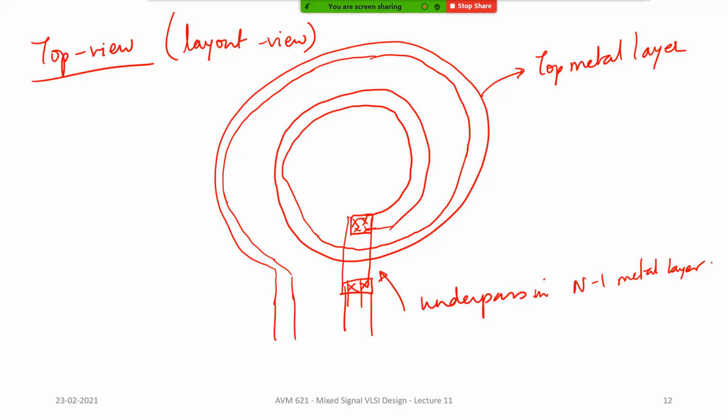So this basically has a certain outer diameter, width of the line, and then you also have spacing, right? This is the spacing, and number of turns. So all these factors basically determine the L and also the Q. Of course, what is not in your control is basically the thickness and conductivity of this metal and other things.